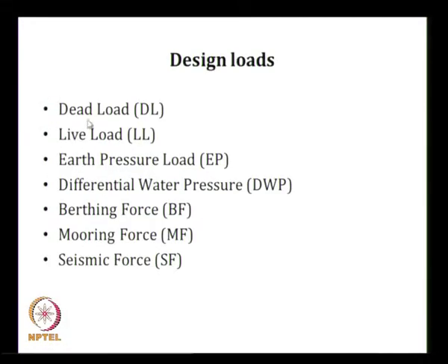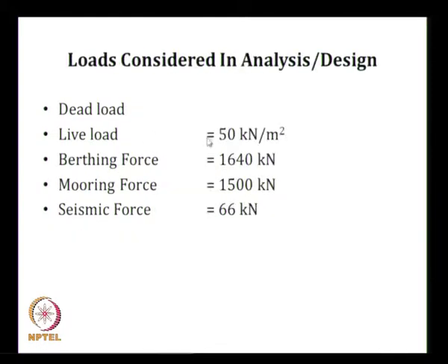We have to design it for these various forces: dead load, live load, earth pressure load, differential water pressure, berthing force, mooring force and seismic force. So we will be computing all these forces. In the live load you will have uniformly distributed live load, mobile harbour crane load, and quay crane loads. The live load is considered as 50 kilonewton per meter square, the berthing force is 1640 kilonewton, mooring force is 1500 kilonewton, seismic force is 66 kilonewton. I will be discussing the calculation of all these in one of the classes.